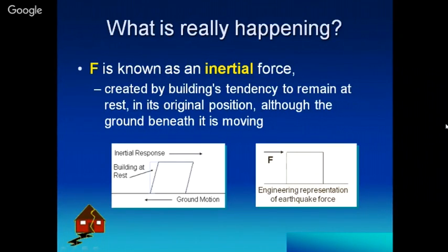The building is at rest, then it starts moving, and an equivalent lateral force is applied to the structure, which is also known as an inertial force, created by the building's tendency to remain at rest. The building is at rest and then the ground starts moving, and due to that there is movement of the building also, due to the inertia force of the building mass.